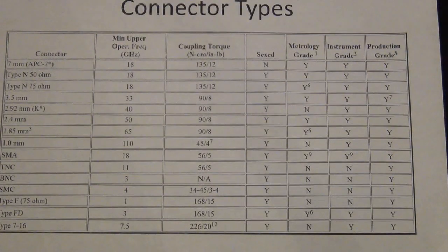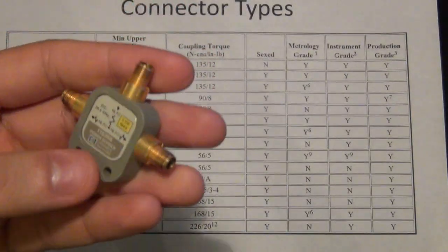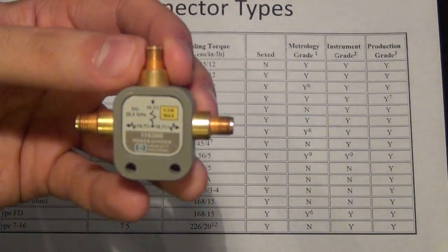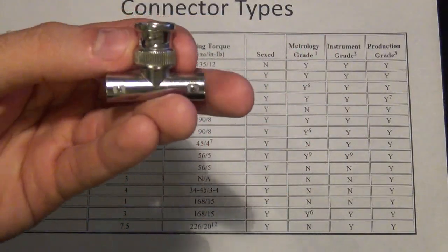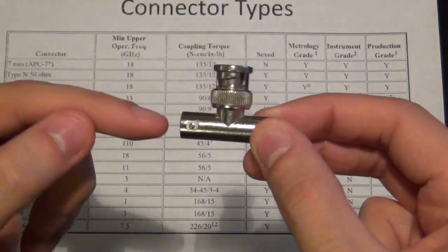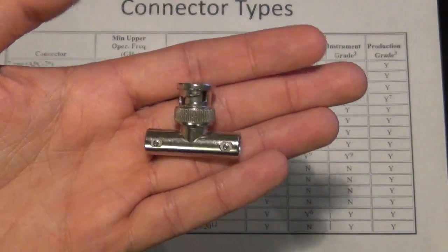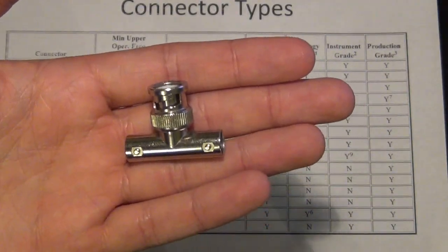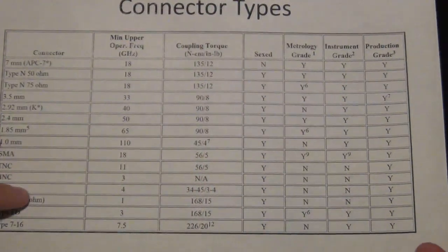Now there are other ways to divide the signal. There are two main ways where microwave circuits divide signal. If you need to divide the signal power two ways, so for example you put in a signal one way and then you want to divide the power into two ways, you can just use a T-junction like the SMA here. Because you have to think about this very easily. If I put 50 ohm on this side and I put 50 ohm on this side, then when I look into this terminal, I will not see 50 ohm, I will see 25 ohm, because this 50 ohm will appear directly in parallel with that 50 ohm. So then I will break the characteristic impedance of the system. This port will have a 25 ohm impedance, which is not good. So in order to maintain that impedance at 50 ohm, people do a resistive power splitter like this one.